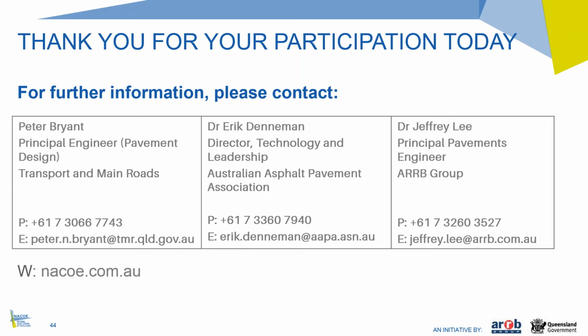And another question from David. The method requires 27 beams. How is it expected that the beams will be produced to get 27 identical samples? Actually, that's a very good question, and we're not looking for identical specimens, because what we're looking for is the normal or natural variation in the asphalt properties that you would encounter with a mix.